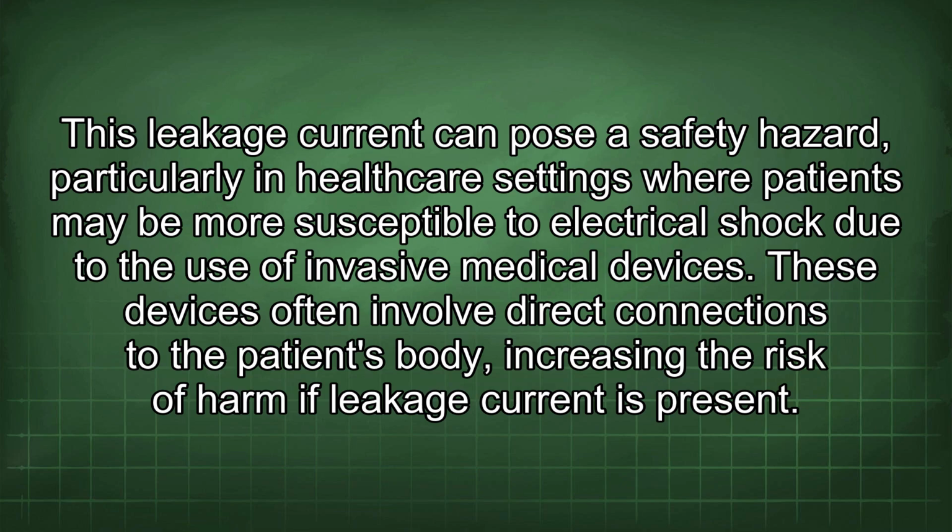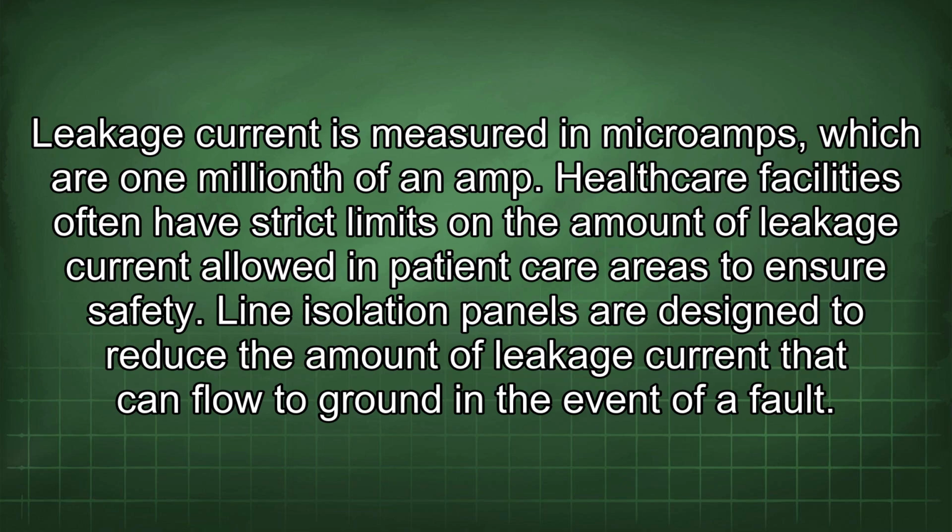These devices often involve direct connections to the patient's body, increasing the risk of harm if leakage current is present. Leakage current is measured in microamps, which are 1/1,000,000th of an amp. Healthcare facilities often have strict limits on the amount of leakage current allowed in patient care areas to ensure safety.